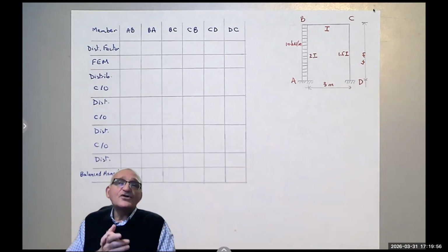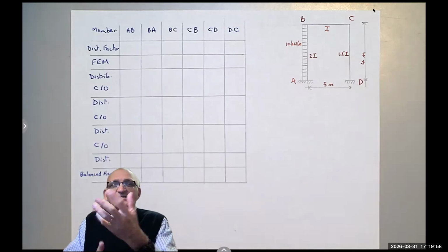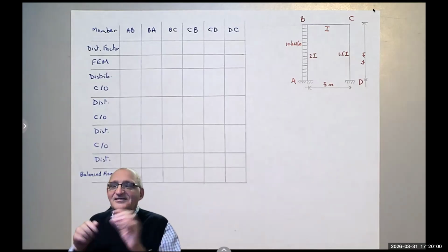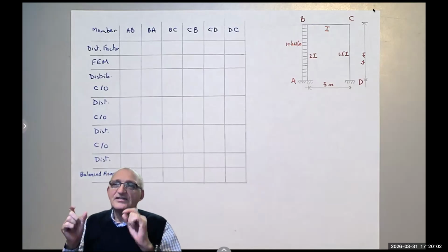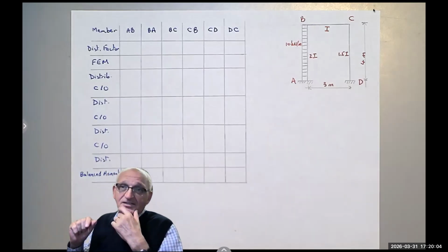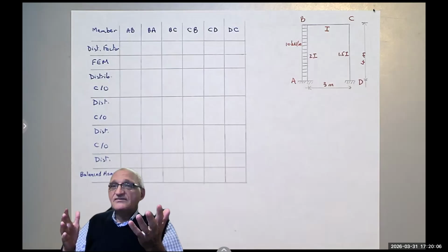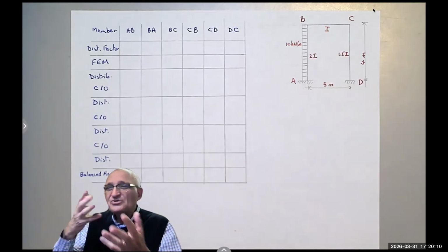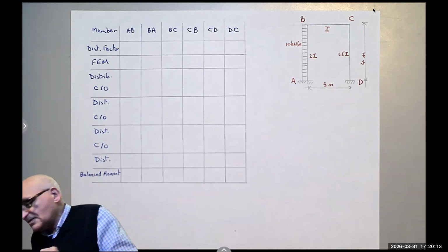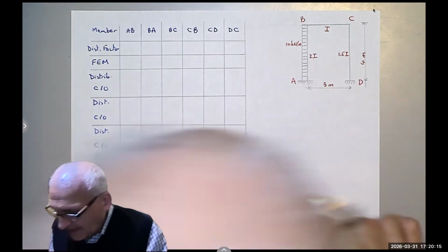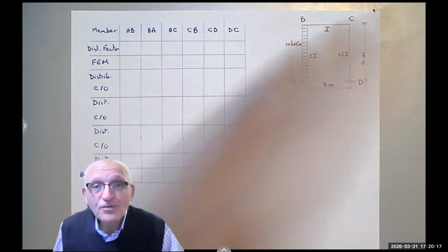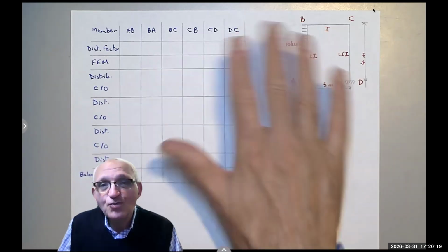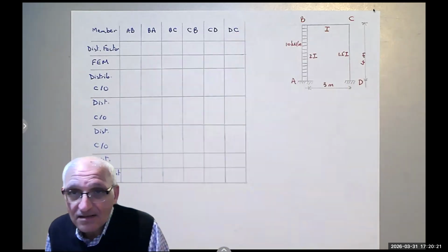Well, in the first part, we would do something similar to what we did when we were trying to find the deflections in a truss member, and we said if there was no load applied, we apply a fictitious load. We'll do something similar, but not quite the same. If I leave that load like that, there would be a sway in the frame.